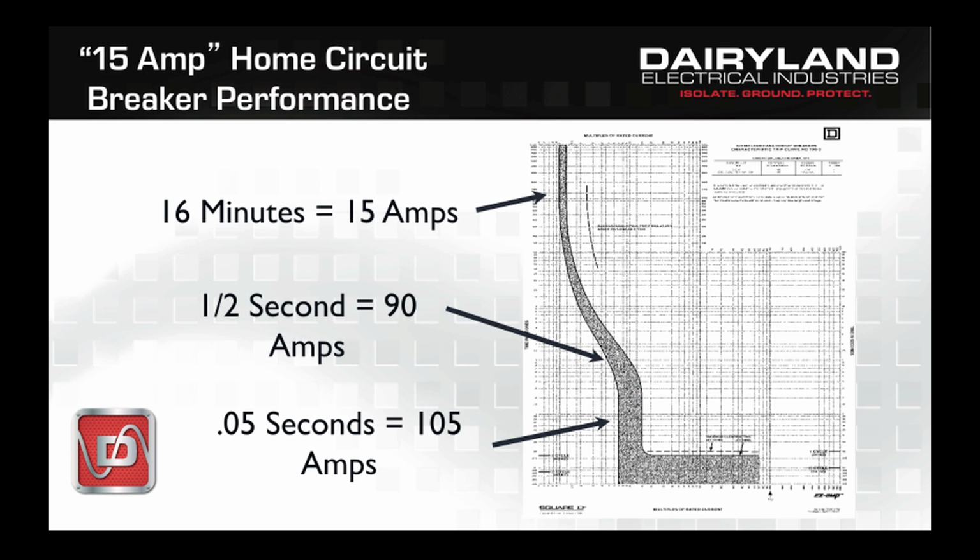To further understand AC fault conditions, we need to take a brief look at AC circuit breakers, since not only power lines but pipeline devices actuated by AC voltages are all protected using them. To make this understandable, I'm going to talk about a typical home 15 amp circuit breaker. Even though we may call this a 15 amp breaker, it's very important to understand that the 15 amp rating only has meaning for long periods of time.